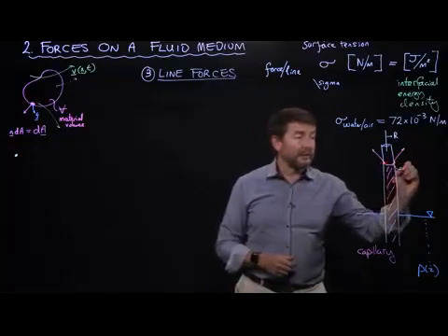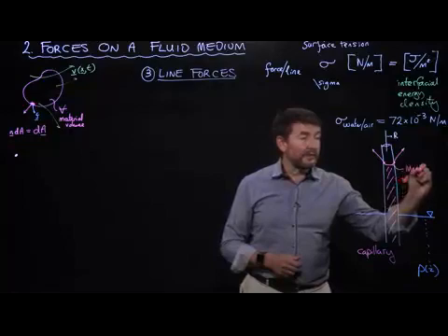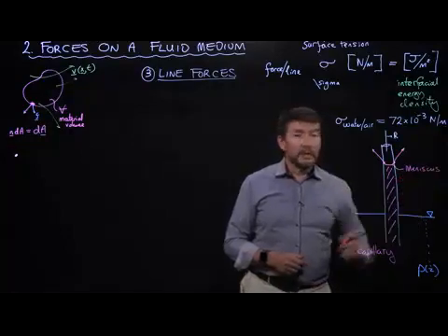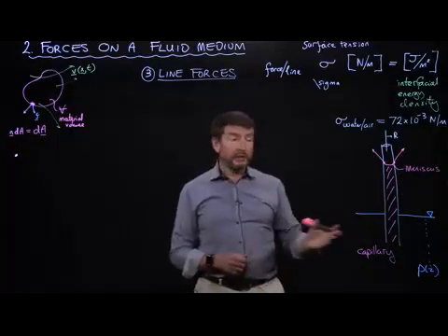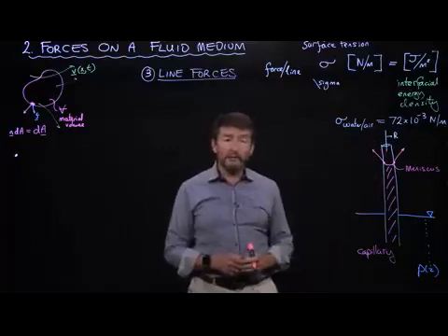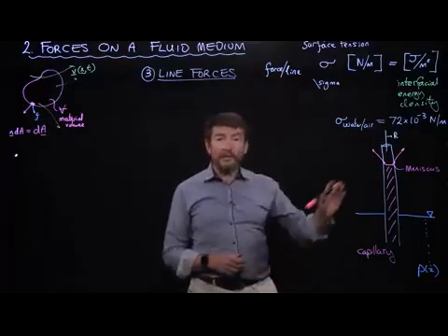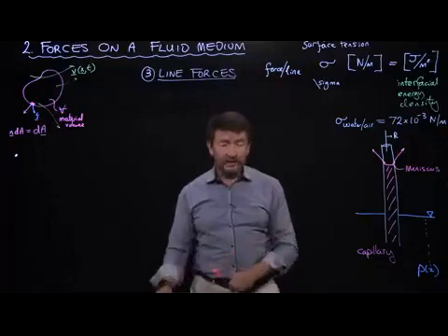And so this free surface is often called a meniscus. The particular height that this will climb will depend on the radius of the tube and also the shape of the surface that the liquid takes.